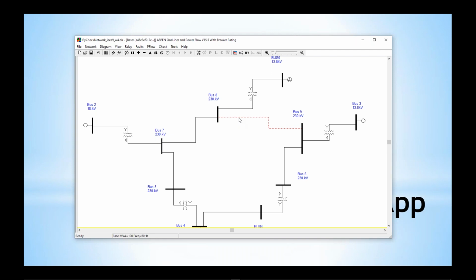Now, if I select this item where I want more or less the network to be, this demo will show you a Python script that takes as input the line I have selected and then runs the network reduction command to produce a network equivalent, eliminating all this around it and showing just the part that I need.